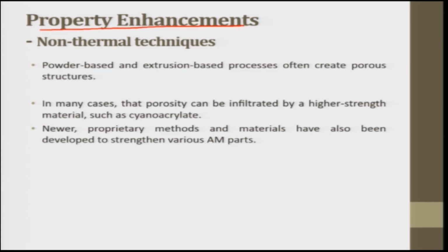Property enhancement, non-thermal techniques. Powder based and extrusion based processes often create porous structures. In many cases, that porosity can be infiltrated by higher strength materials such as cyanoacrylate. Newer proprietary methods and materials have also been developed to strengthen the various additive manufacturing parts.